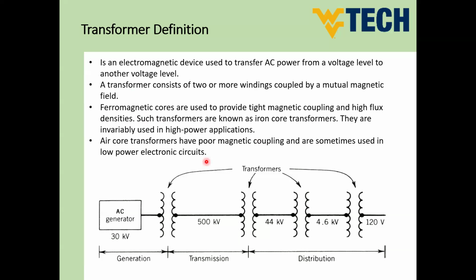In this case, you can use a transformer inside a circuit breaker, but this transformer is going to be an air core transformer. Why? Because for any core transformer, if the current increases relative to the normal ratings, the core may be saturated. And if the core is saturated, you will lose the function you need of this transformer.